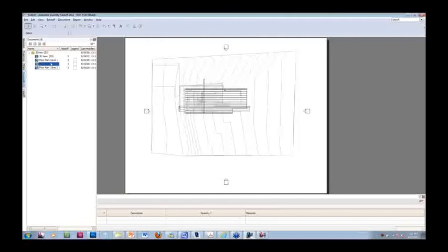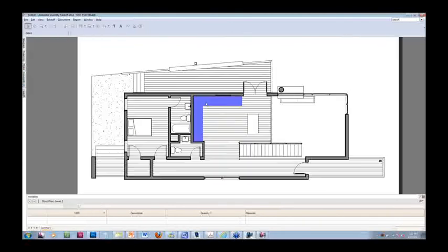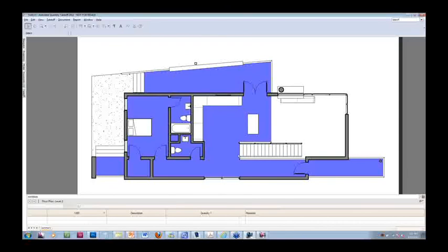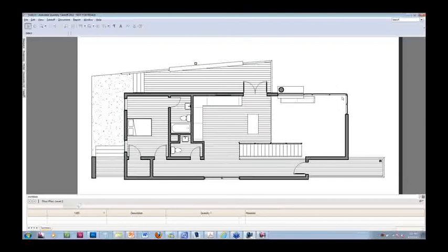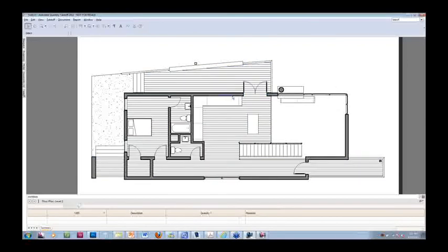And then what it means is that you're seeing pretty much every floor, and you can also do the same selection and tracking and counting within the plan just like you do in 3D, and you do it once. So even though you do it in plan, it does remember if you go back to 3D. So it means that it knows what's been tracked, and it automatically selects everything, not only on this plan, but also in the previous or in the next level.